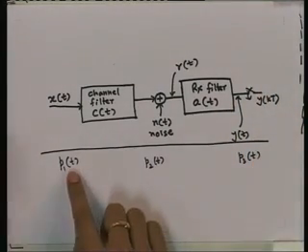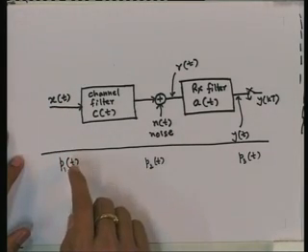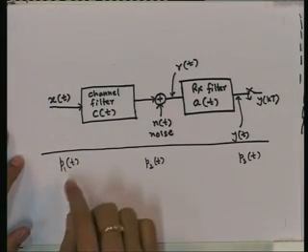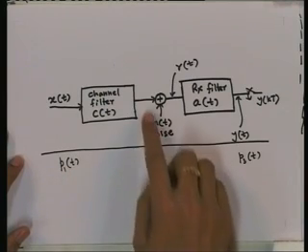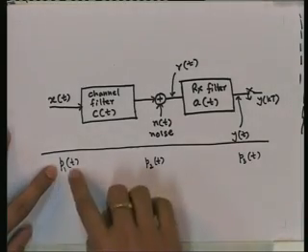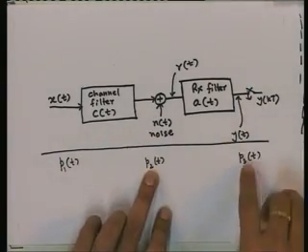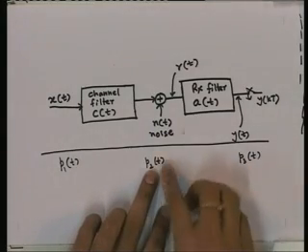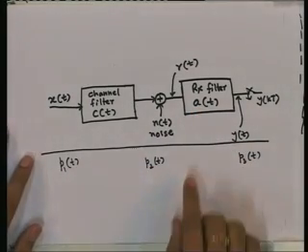Here x(t) is a summation of scaled and shifted versions of the pulse p1(t). The output of the channel for p1(t) was called p2(t), which is the convolution of p1(t) and c(t), and the corresponding pulse at the filter output is called p3(t), which is p2(t) convolved with a(t).